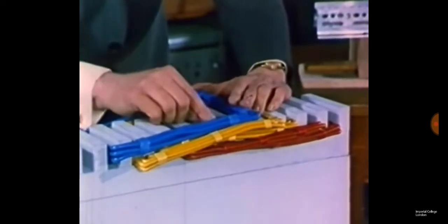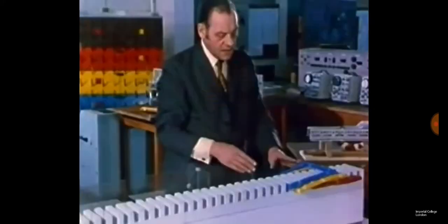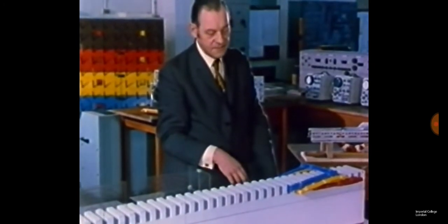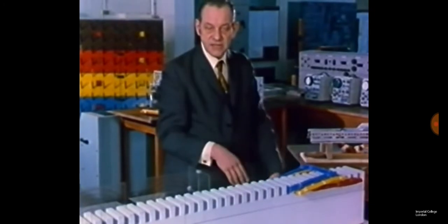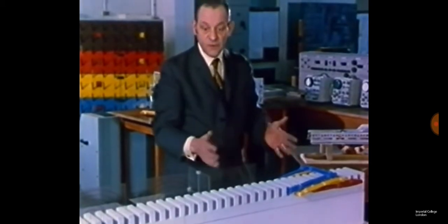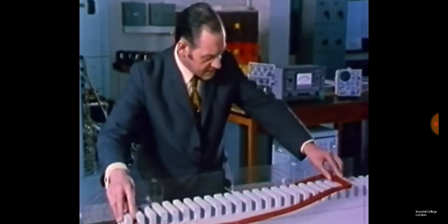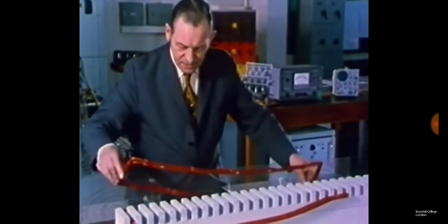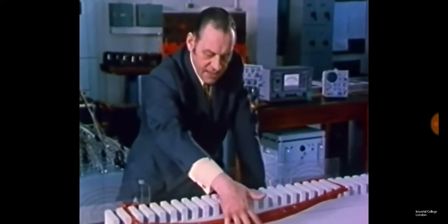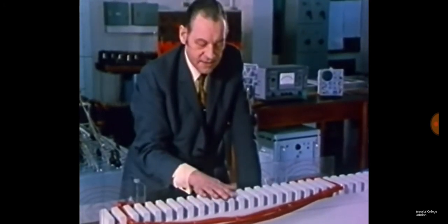Not only is it waste, but it produces a magnetic field of its own, which does nothing except waste your applied voltage. Now, what length of coil would you need to have to produce a traveling magnetic field at 250 miles an hour? The answer turns out to be 4'6". So can you just imagine how these problems would be magnified when you have to deal with coils 4'6" long? You'd be putting one end in a slot over there and the other one 4'6" away over there. And then the next coil. And so on. And this end winding would have built up to something quite impossible by the time you'd filled all these slots. And that's as far as the electric circuit's concerned.